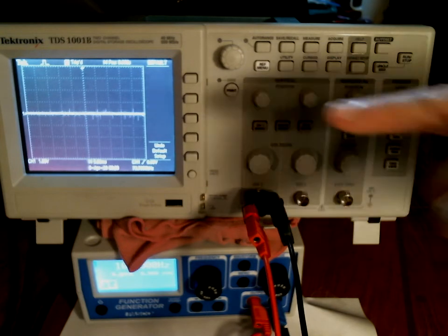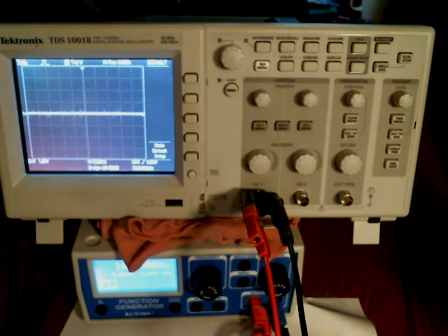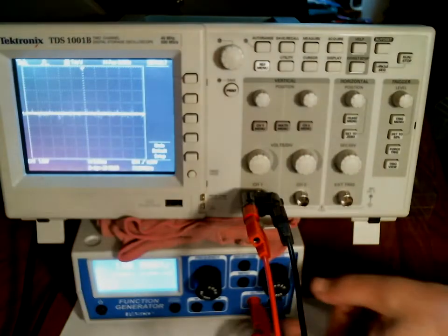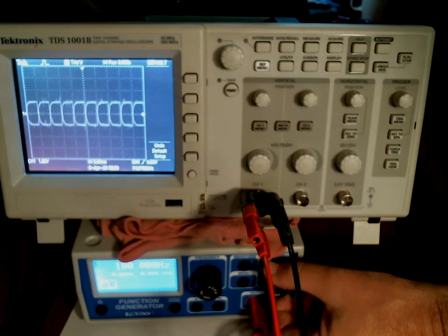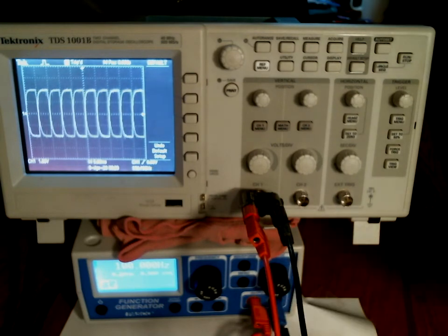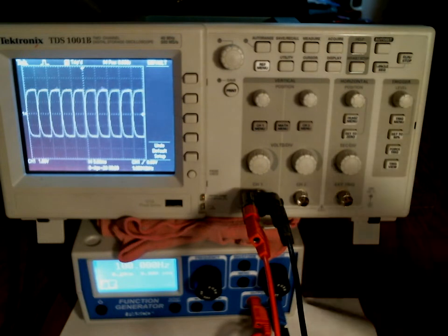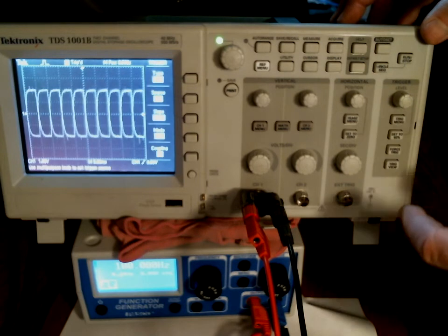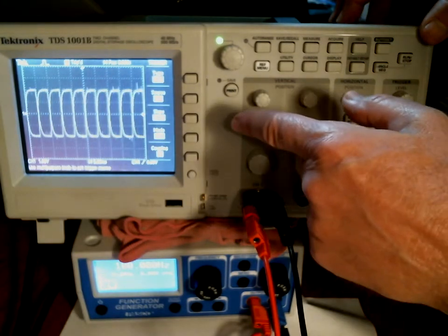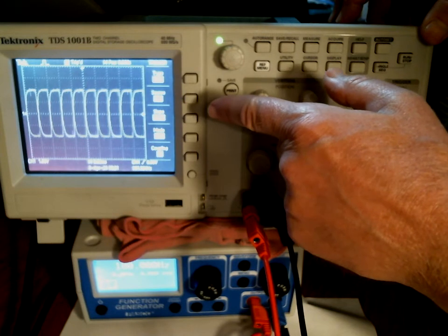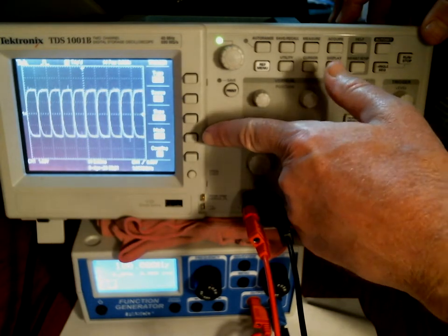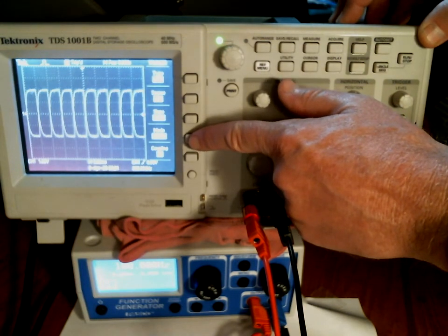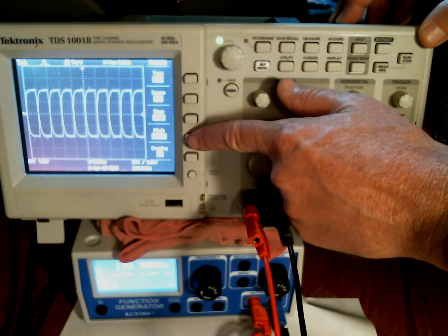I don't actually have any voltage on the scope because the function generator is turned off right now. But I'm going to turn the amplitude back up. So now I get a trace on the scope. And it looks kind of funky because it's not triggering correctly. If I push trigger menu over here, the white highlighted blocks of text are too hard to see on this video because they're too bright, sorry. But right now it says mode auto. So now I'm going to change that to mode normal, which gives me more manual control over the triggering.